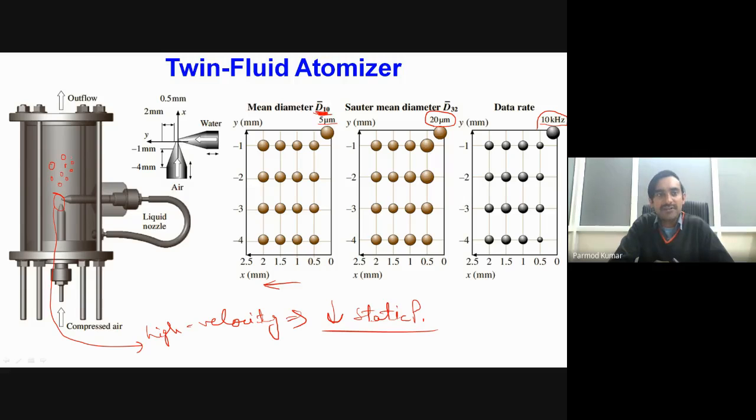We may have very fine droplets and very large droplets also. So we require a certain mechanical arrangement as a separator for removing the large droplets out of the stream coming out of this outlet. This type of atomizer is referred to as a twin fluid atomizer, which is required for generation of liquid seeded particles.